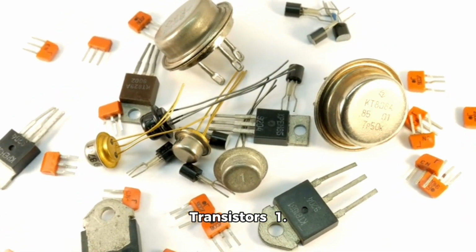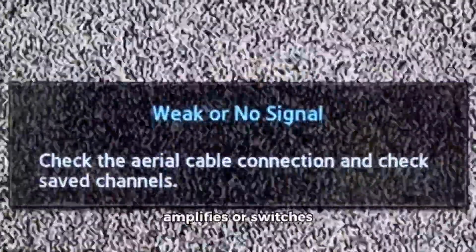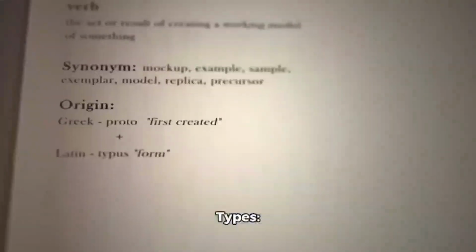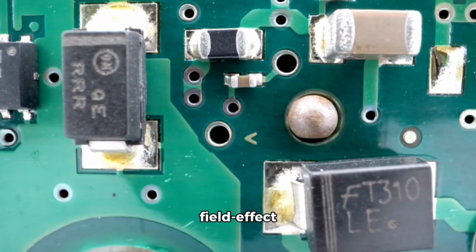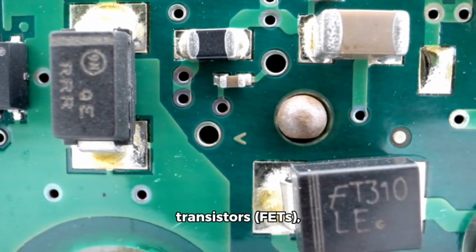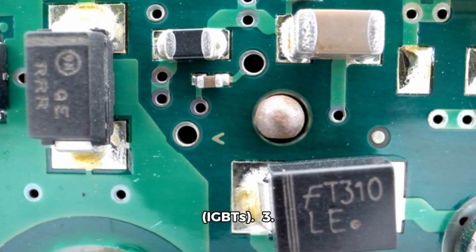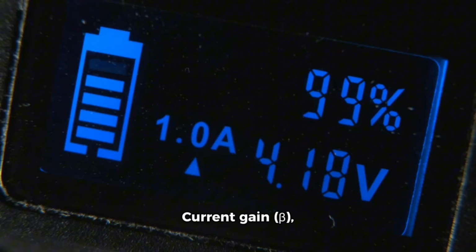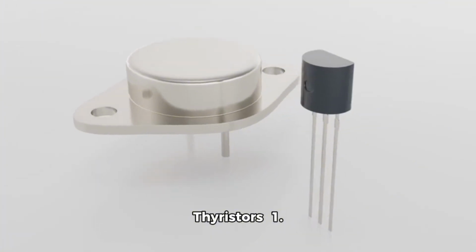Transistors. 1. Definition: a component that amplifies or switches electronic signals. 2. Types: bipolar junction transistors (BJTs), field effect transistors (FETs), and insulated gate bipolar transistors (IGBTs). 3. Characteristics: current gain beta, voltage gain, and power rating (P). 4. Applications: amplification, switching, and logic operations. Thyristors. 1.